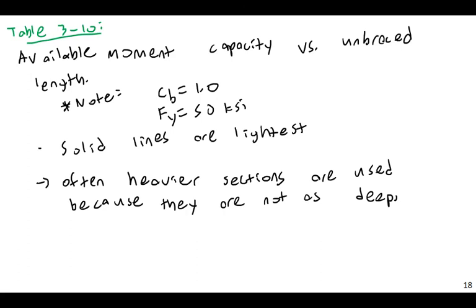So I can make my beams really, really deep. But the problem with that is, as my building gets taller, it's going to be self-defeating at a certain point, because I am then going to end up gathering more wind load, and that means my columns are going to have to take more load, et cetera, et cetera. All of this is intertwined, as you've probably already seen in some of your design work before. Okay.